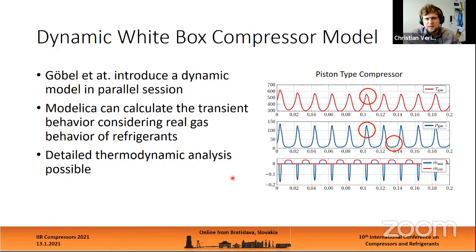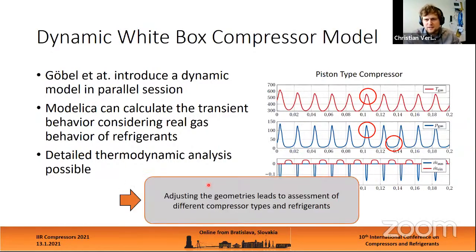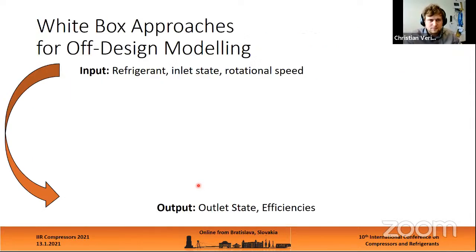And Modelica is able to calculate these transient behaviors considering different fluids, and now we are able to cover detailed thermodynamic analysis. So just, which is my part of the paper, adjusting the geometries leads to assessment of different compressor types and refrigerants for now.